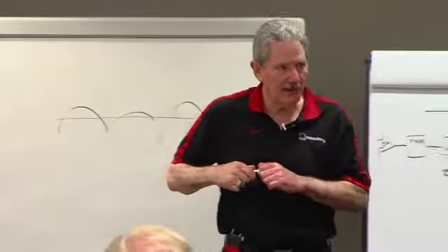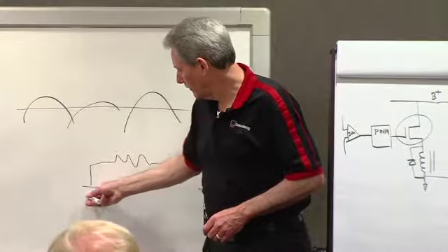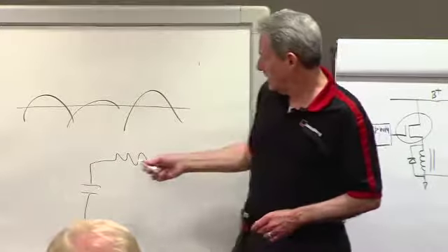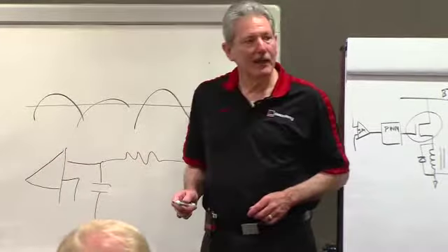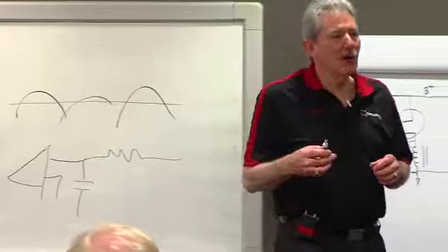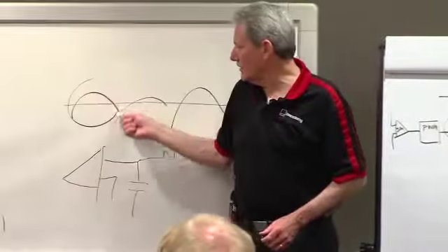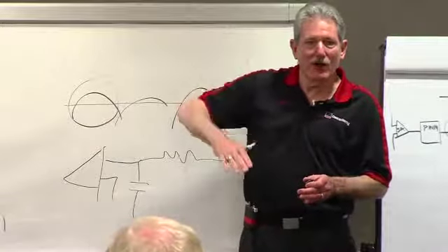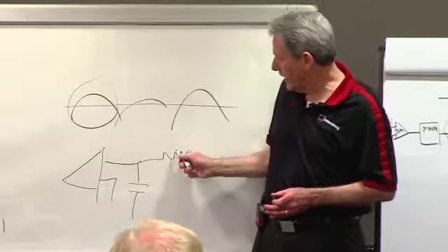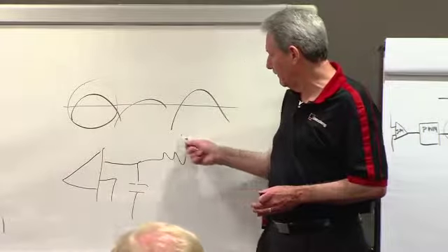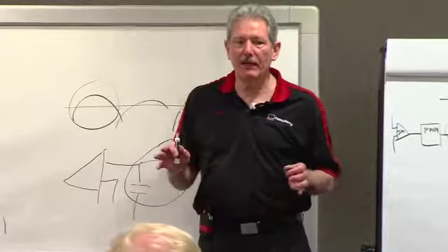If, on the other hand, you can go through a filter and then send this through a comparator, now you can get a direct reading. You're using the ripple as a switch to turn it on and off. It's bang, bang, bang, bang, bang. On this, I can now take a long filter and apply that here, and it's really refined.